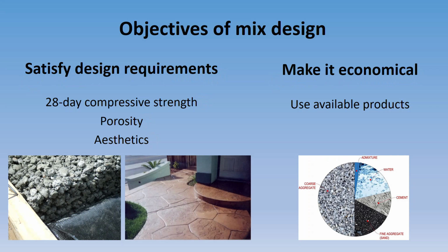Architects are finding they can use concrete in a lot of different ways with colors and textures and patterns to make really, really nice looking finished products. And engineers are finding that they can use concrete as a draining material. So this example over here, this was a parking lot that we worked on, and you can see it's a very, very porous concrete. It's specifically intended to allow water to drain through it and basically eliminates surface water runoff generation from things like parking lots.